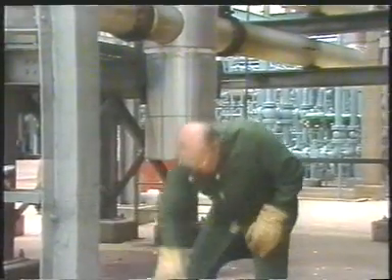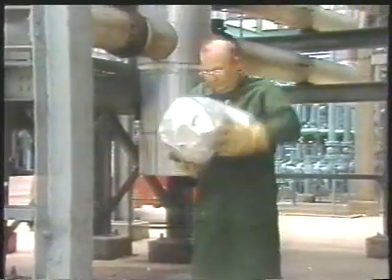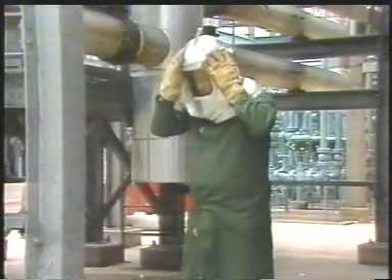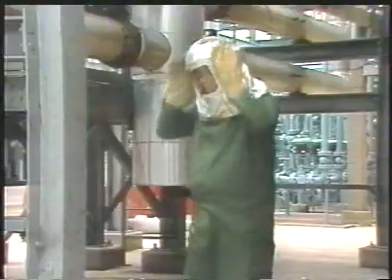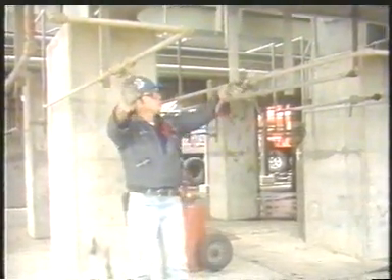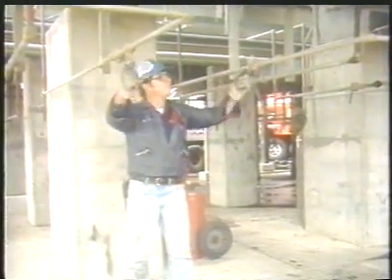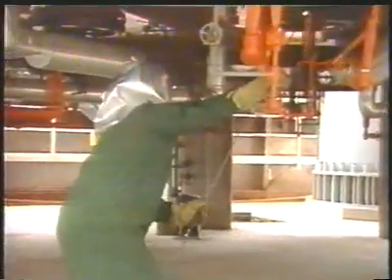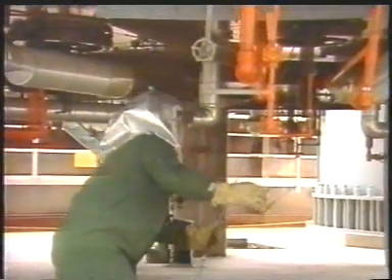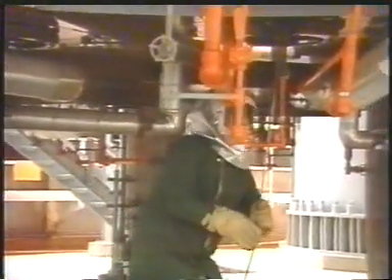Before starting the lighting procedure, you may be required to put on special protection light-off gear. Check your safety regulations to see if this equipment is needed. The next step in the lighting procedure is to check that all fuel gas valves are shut tight and then remove the fuel gas blinds. Each pilot must be lit separately. Light a pilot at each end and then one in the middle to provide a source of ignition throughout the furnace.